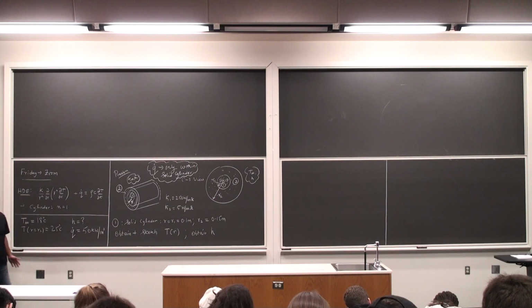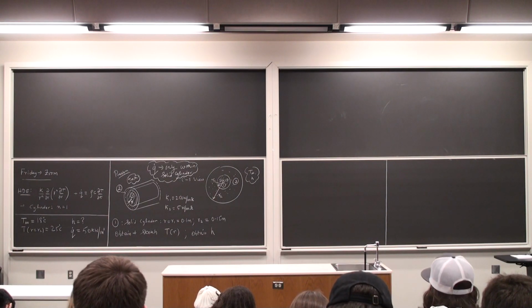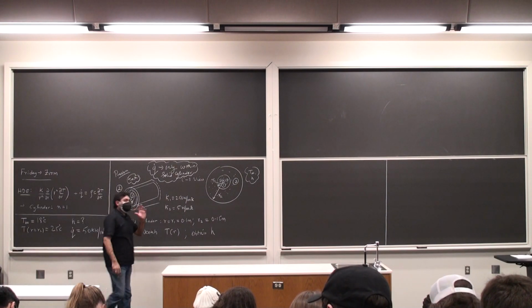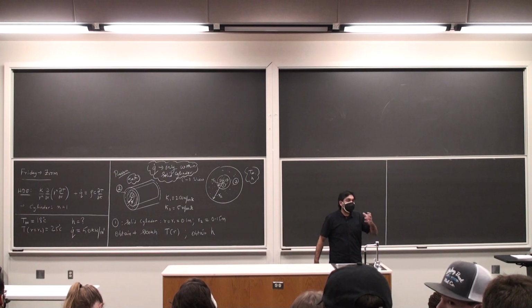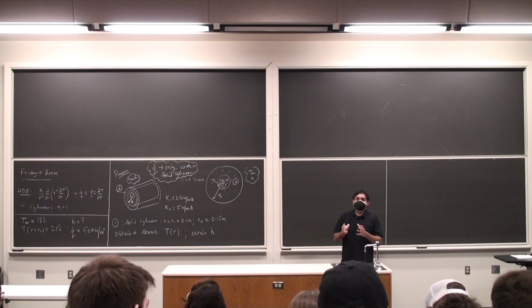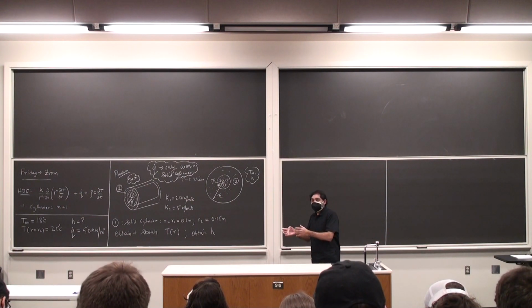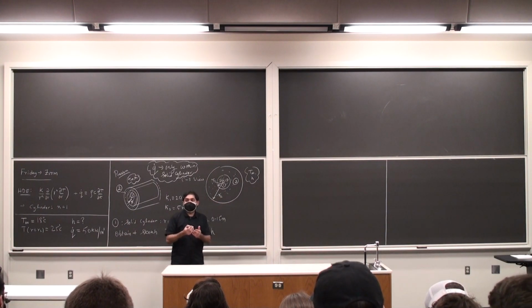Which means that the Q dot for the ring is 0. There is no heat generation taking place within the ring. So you can think of an application. This could be the core of a nuclear reactor where there is a large amount of energy being generated. It's very hot. You want to prevent the temperature of the core from declining below a certain critical value, and so you surround it with insulation.